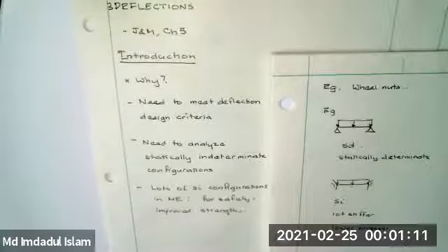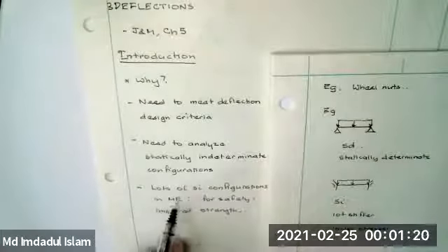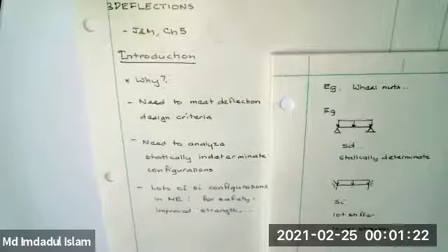And so you lower the stresses, I think, if memory serves me rightly, maybe 33%. Okay. And that's significant in fatigue. So these are the reasons we're going to do statically indeterminate structures. And as the word statically indeterminate says, you cannot just solve them with statics. You have to go look at the deflections, otherwise you can't do them.